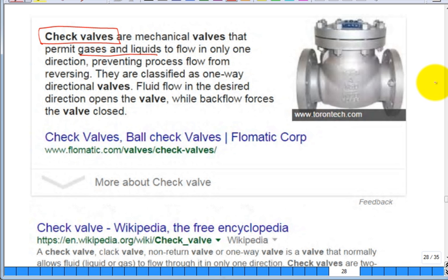They're all over the place. Anybody have a well? Maybe you're all on the city water service, but you have the submerged well, and it's way below the ground surface. If you didn't have a check valve, right in here, the water pump in the submerged well would kick on. You would push water up.